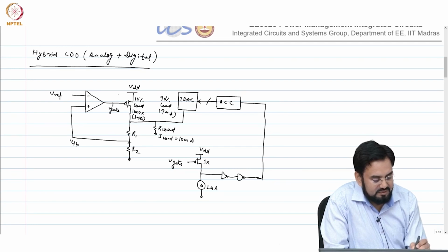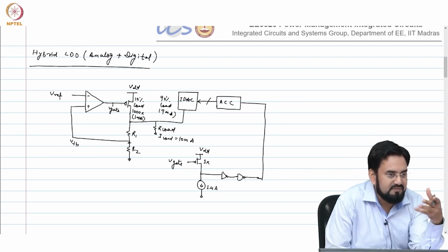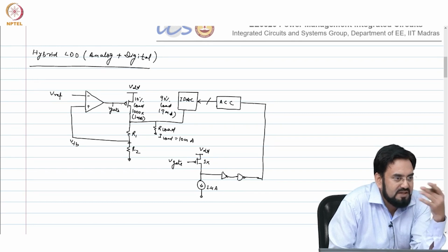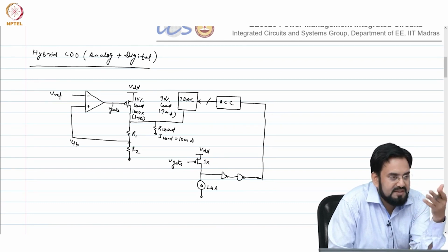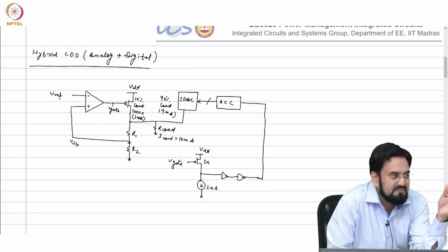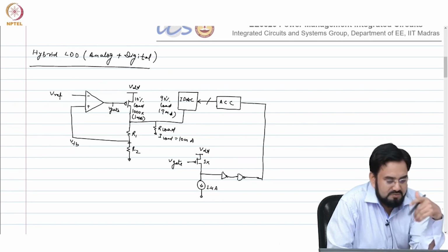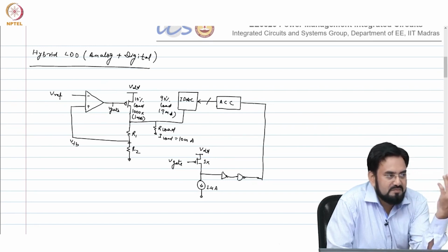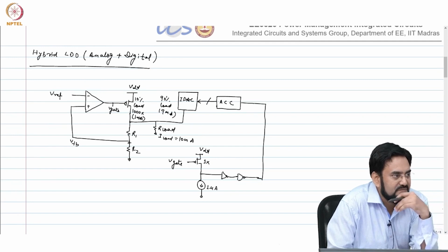We know that you have sized your device for 100 millivolt overdrive, and now let us say VDD minus VGS, the difference becomes 1 volt. So 100 millivolt to 1 volt is a 10 times increase, and you know that's a square. Your size is same, mu Cox is same, so your current will go 100 times. So instead of 1 milliamp, it will start drawing 100 milliamp.